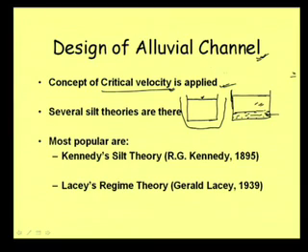Say from a river, the depth on this side will always be higher, and generally when we do irrigation, suppose from here we are collecting water and supplying it on this side. To what extent can we go? This canal moves like this, and to a certain extent we can go. What is the command of that canal? The command of a canal means to what extent this canal can carry water.